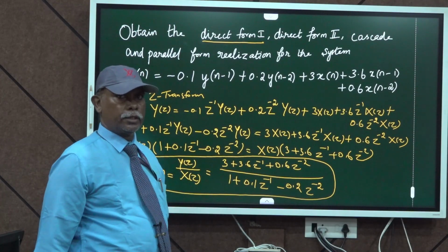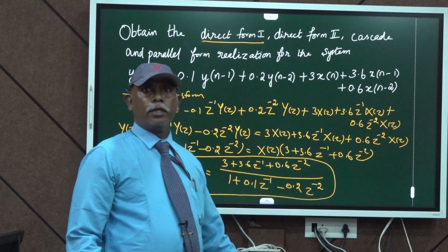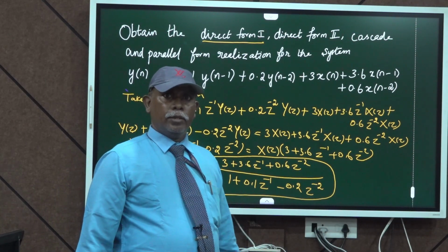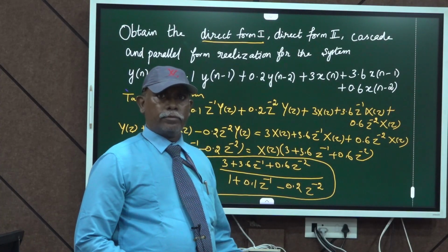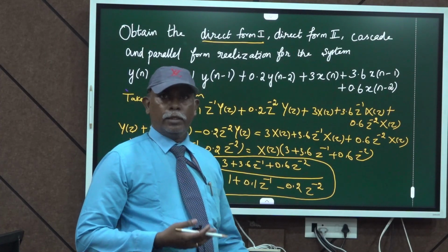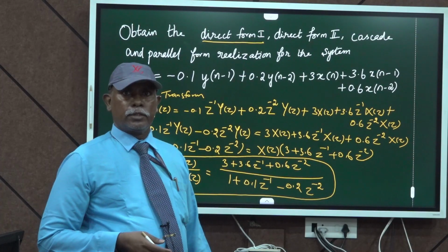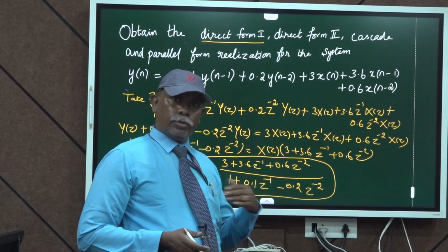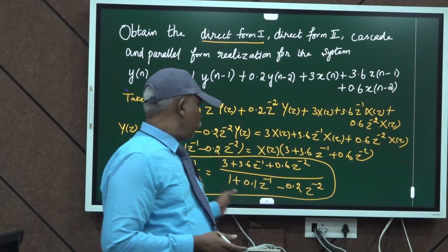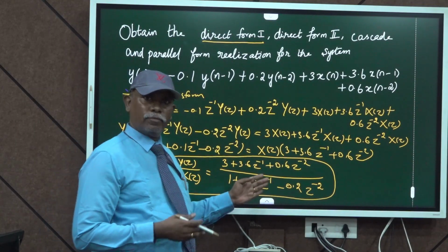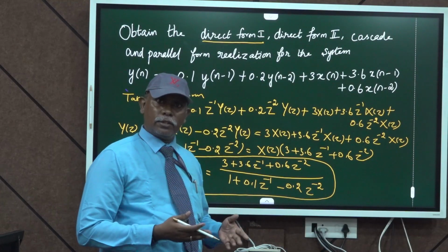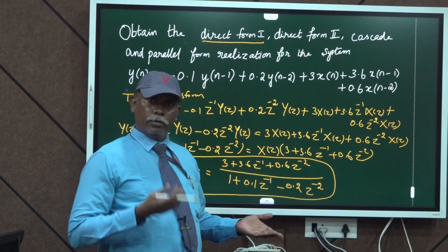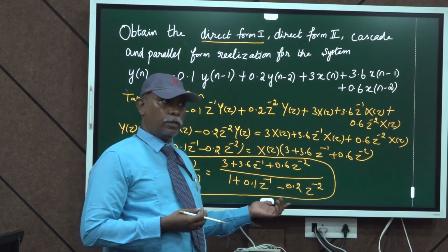So how do we construct direct form 1? I want to draw the direct form 1 structure. Drawing is very easy. Please see that. This type of structure is available in the computer or DSP processor for practical implementation. So x of n, your speech signal, is coming. Here the constants are there. These constants are called filter coefficients. Your speech signal is multiplied with these filter coefficients.